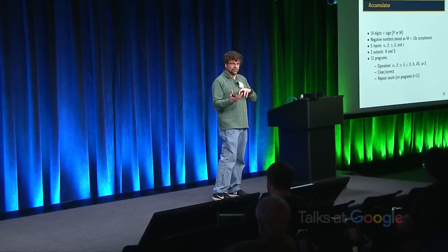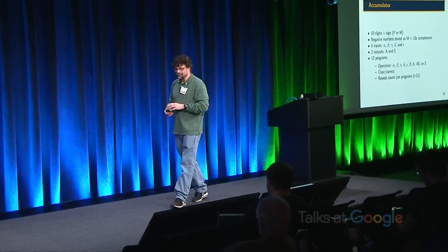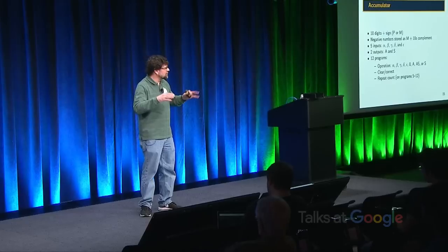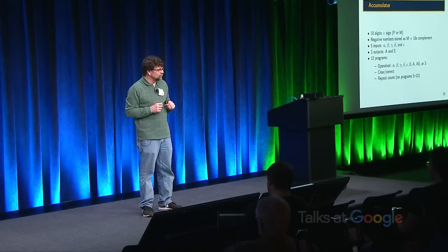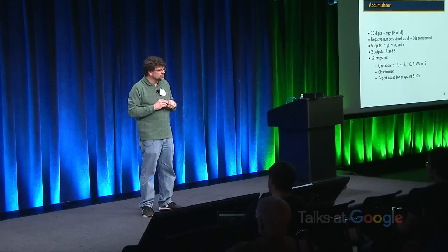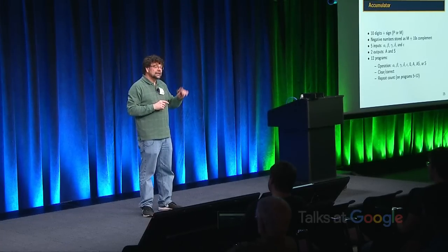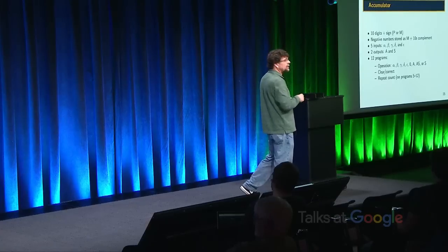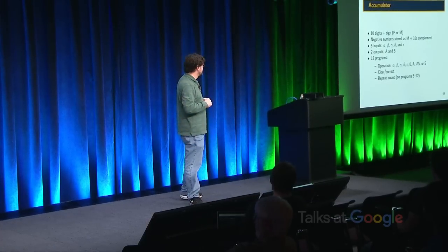That same control, if I'm receiving, I actually get an extra 1 added in. And that has to do with the 9s versus 10s complement. You may remember, going all the way back to your freshman year in college, when you were taught about 1s and 2s complement. 1's complement, you flip all the bits. For 2's complement, you flip all the bits and add 1. Same sort of thing happens with 9's and 10's complement. To get from 9's complement to 10's complement, you just add 1. And so that correct setting is about adding an extra 1 for that.